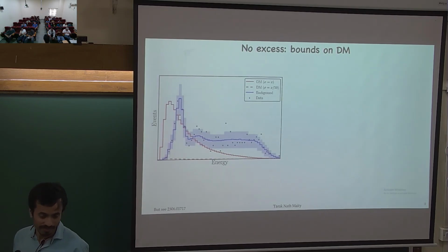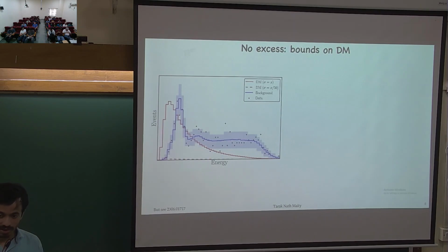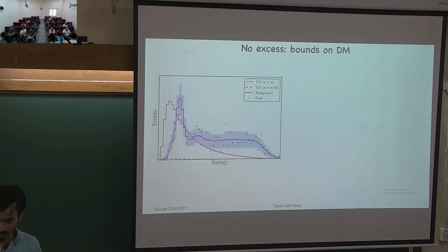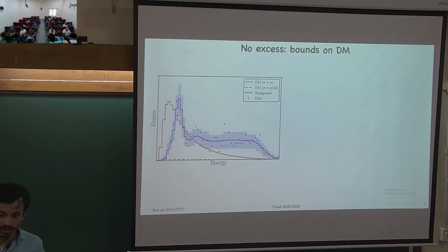No, so they do not know what the excess is, but definitely not dark matter. One of the reasons that could produce this kind of exposure-independent thing is that while you are reading out, you are essentially applying some voltage differences between the pixels, and that could create some spurious charge and spurious holes that could appear over here.